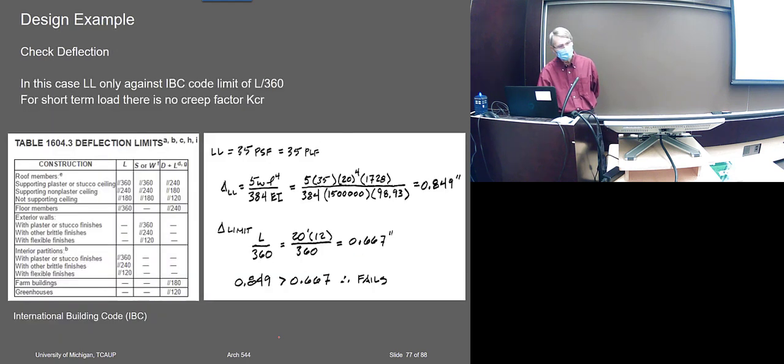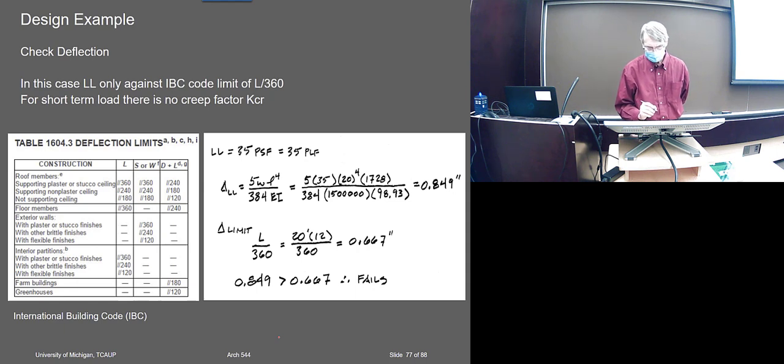And then this one we did a little deflection check, live load deflection, just for fun. The limit on floor members, I guess, is this L over 360.